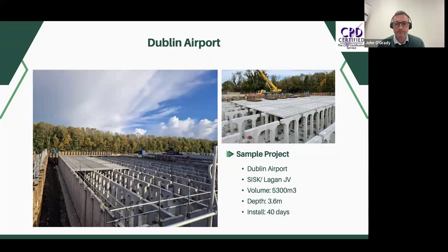Dublin Airport, we've been heavily involved there. The North Runway, which hopefully will be used at some stage. We would have installed, I think, 9 large attenuation tanks, anywhere from 5,000-6,000 cube up to about 10,000. And they were all airside, and that's the accidental loading design stuff that I mentioned earlier. This one, thankfully, wasn't airside, but was completed, I think, about 18 months ago.